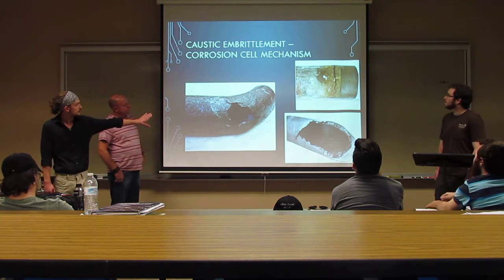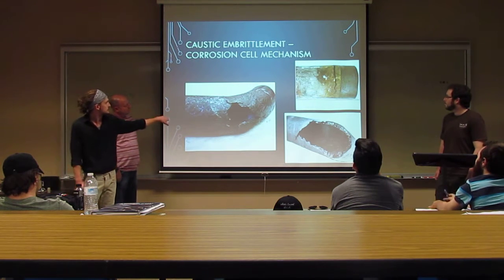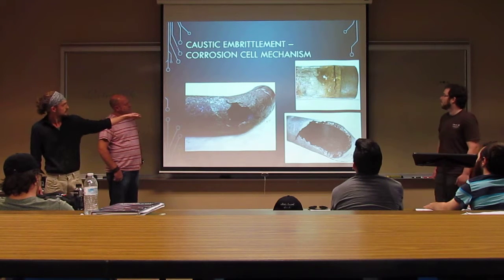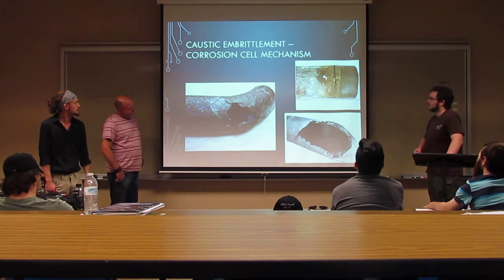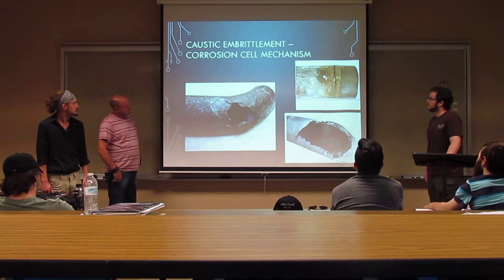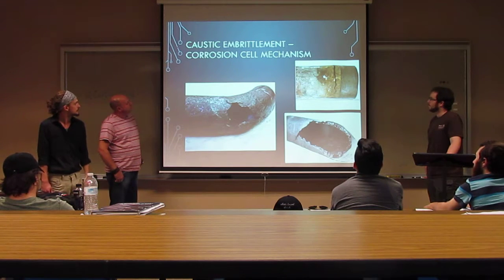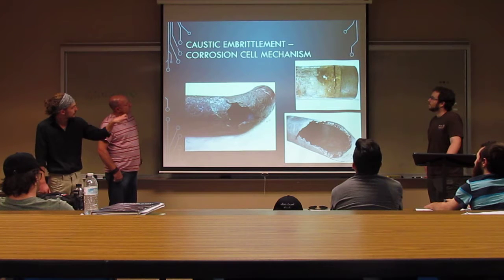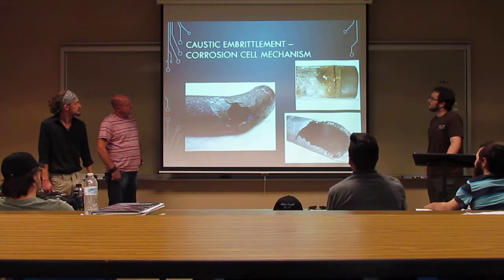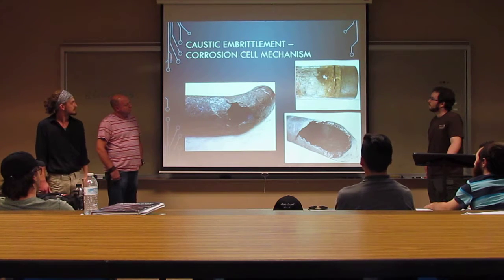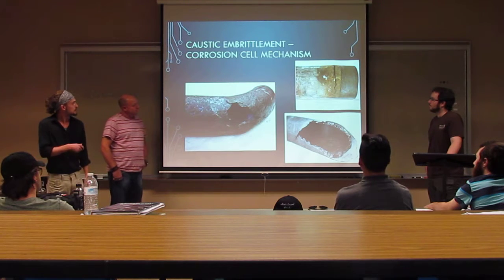This is like those areas I was telling you about. It's not necessarily even a 90, it's kind of 30 or something. But right there, the erosion corrosion played a part in it as well. But the caustic soda was able to go completely through that part of the metal. I'm not sure that whole piece cracked out at once. I'm pretty sure it was just super thin, and then something happened to it, and it poked right through.